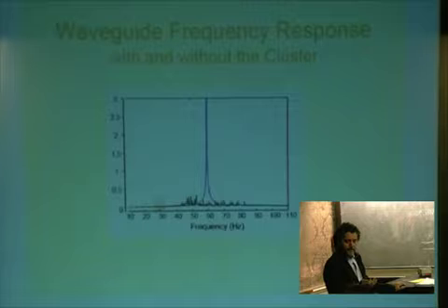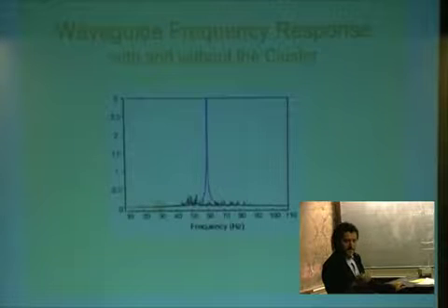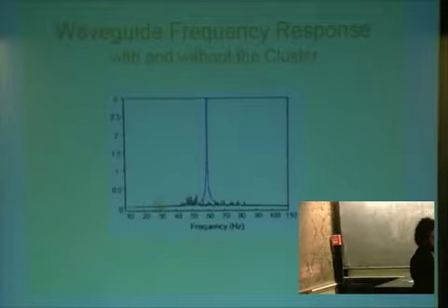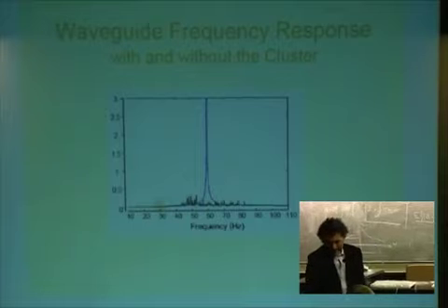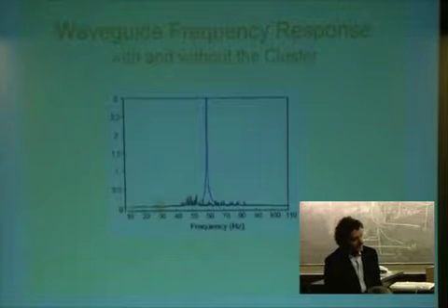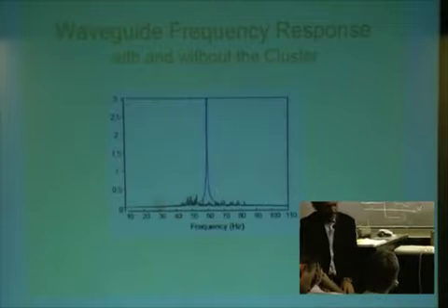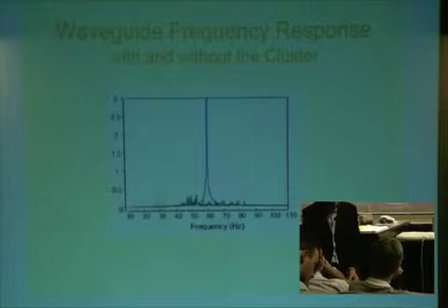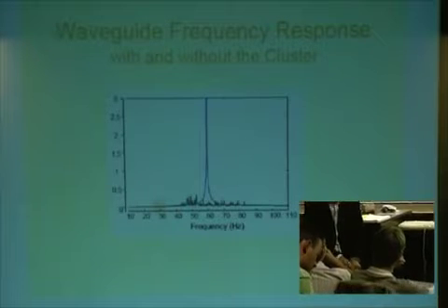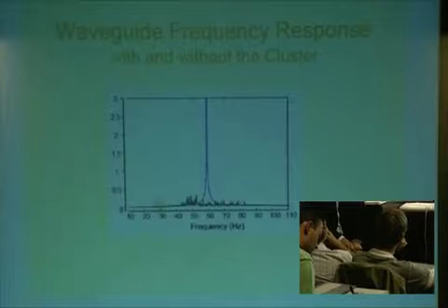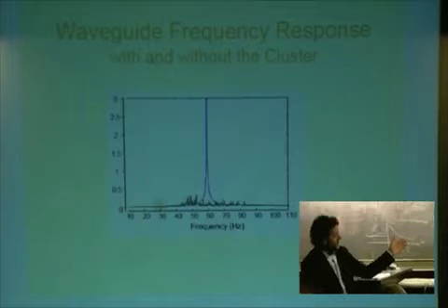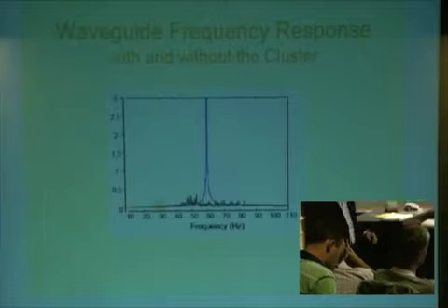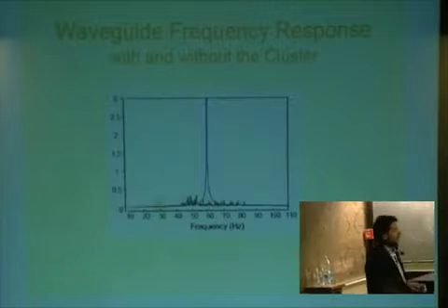It is difficult to produce the same result using a traditional damping system. Damping systems generally put something that has the property of introducing local dissipation. So I want, for example, to damp this. I put a foam over that. That means that I'm trying to transform locally the energy that goes in here into heat. But here the concept is completely different. I'm exciting here. I put here an energy sink, and then I'm moving the energy far away from the point of injection of the power.